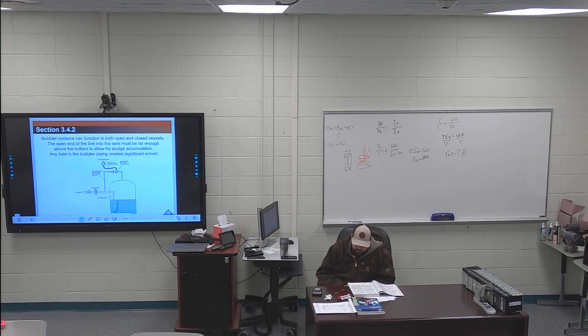Next paragraph, first sentence, is also highlighted. In applications in which the process vapors are corrosive or unstable, or the transmitter must be mounted at a lower level, the low pressure connection line should be filled with an inert liquid prior to calibrating or zeroing the transmitter's output. The low pressure line is then referred to as a wet leg.